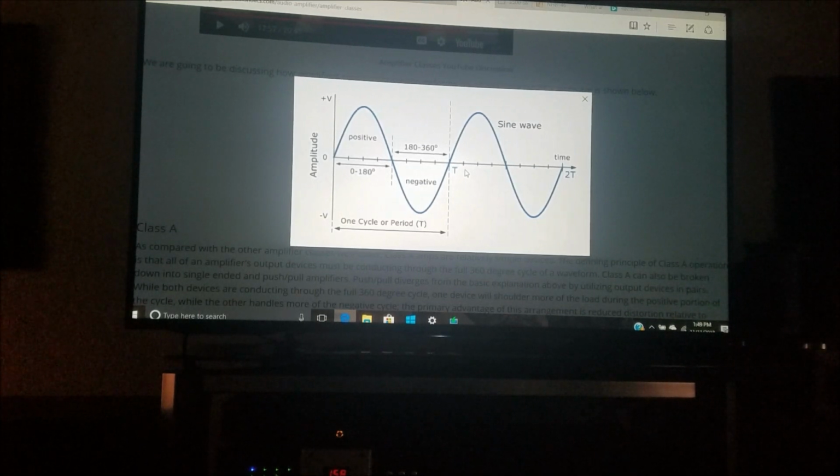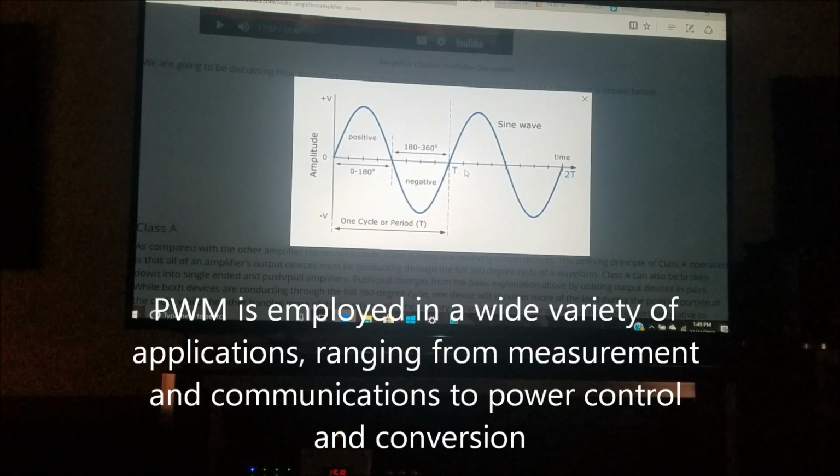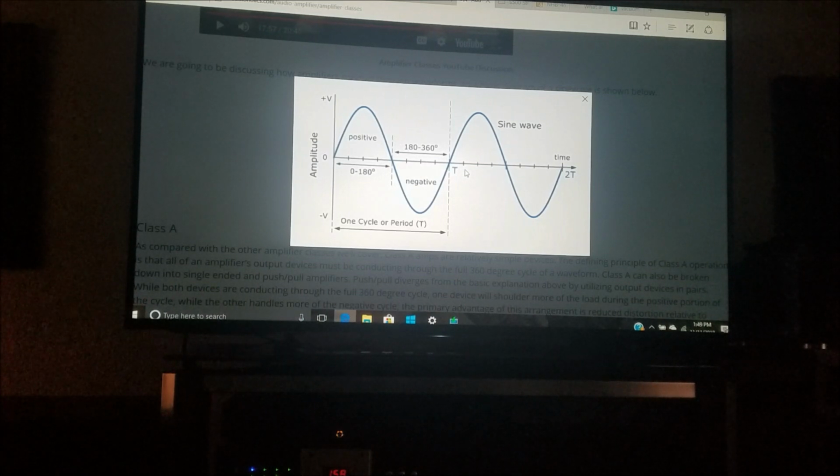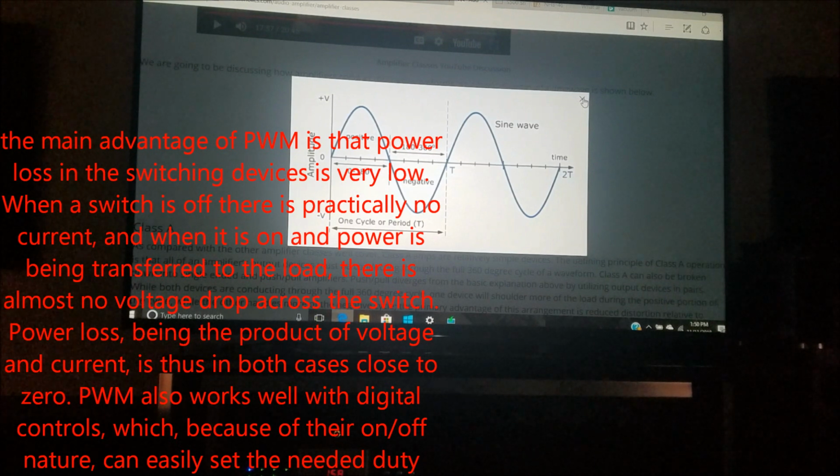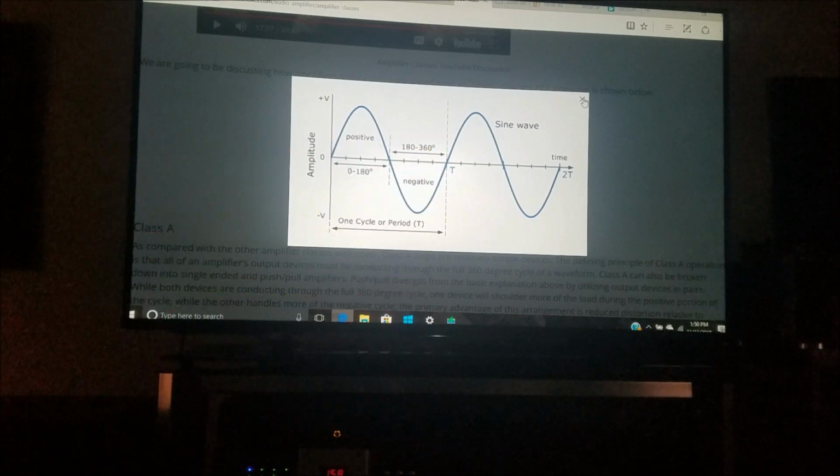You see, the frequency of the output pulses is actually 10 or more times the highest frequency in the input signal that's being amplified, so the filter can adequately reduce those unwanted harmonics and accurately reproduce that incoming signal that was originally there. It's those tops of the waves that we're attempting to smooth off here. You see, we don't want flat lines or jagged edges. We want a nice, smooth, curved sine wave to appear. So what's the biggest advantage of using this pulse width modulation versus having heavily biased output devices, transistors, vacuum tubes, what have you?